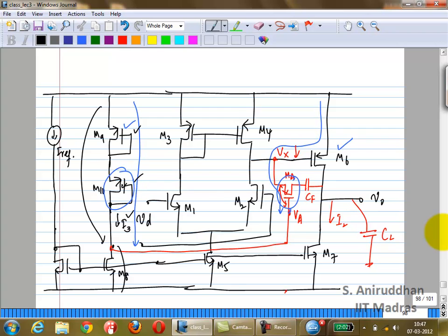How do you ensure that? MA is in triode. Well, because you have a capacitor in series, there is no bias current, right? So it is definitely going to act like a resistor. Yes. Well, yeah, but still you're applying a small signal on top of your bias condition, right?